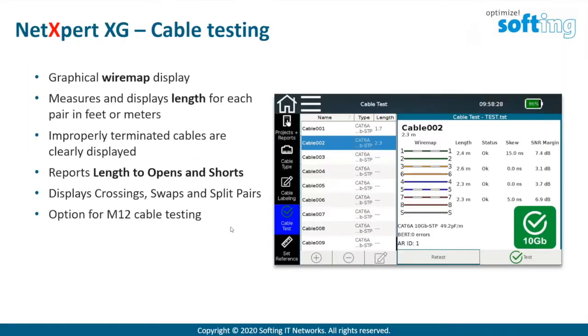So I wanted to show you just a few sample screens of what you see on the display of our XG. And this is one of the basic ones, which is showing a quick test of a cable from end to end. So if you think you're having a problem with the cable, you can easily attach the XG. We have a remote unit, I showed it in the earlier slide, and then the main unit, where you quickly choose what test you want to run. And then within 15, 20 seconds, you get a nice screen that shows you the length of the cable,